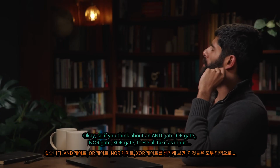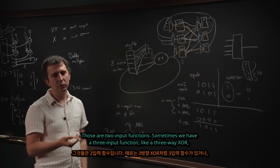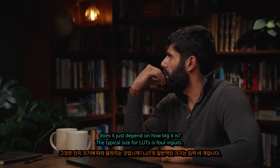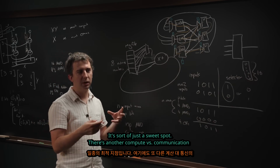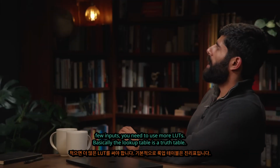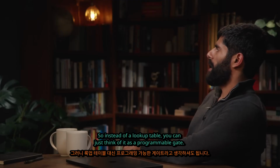Okay, so the lookup table, if you think about an AND gate, OR gate, NOR gate, XOR gate, these all take 2 inputs. Those are 2 input functions. Yeah. Sometimes we have more complicated ones, a 3 input function would be a 3-way XOR, right, or a 4-way XOR. And in this case, how many? It just depends how big it is. But typical size for LUTs is 4 input, which is sort of a sweet spot. There's another compute-communication trade-off here. If it has too few inputs, then you need to use more LUTs. Yeah. If it has too many... But basically, the lookup table is a truth table. It's a truth table. Yeah. And with the truth table, you can program in any gate you want. That's right. And so instead of lookup table, just think a programmable gate.